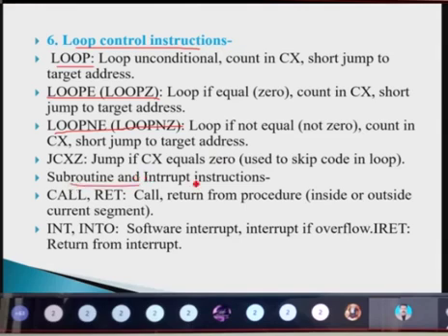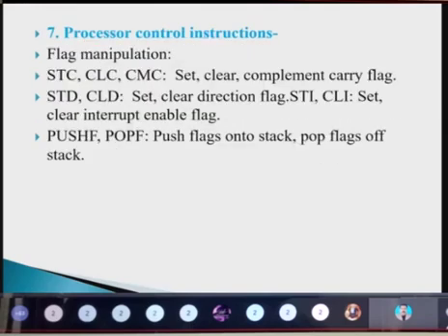And the subroutine and interrupt instructions, like CALL or RET. CALL means if I want to call a procedure inside or outside the current segment, I can do it using CALL. RET means if I want to return from the procedure, I can return using RET. INTO is the software interrupt, interrupt on overflow, and IRET returns from the interrupt. All those things come under these control instructions.